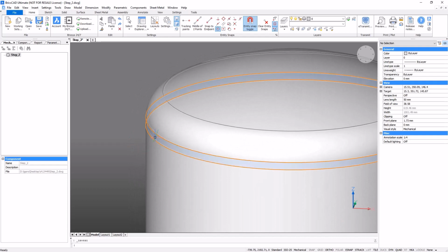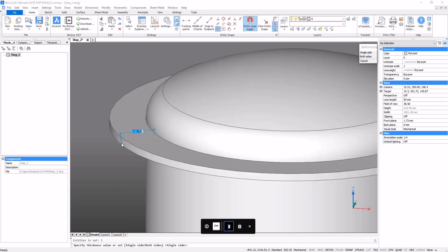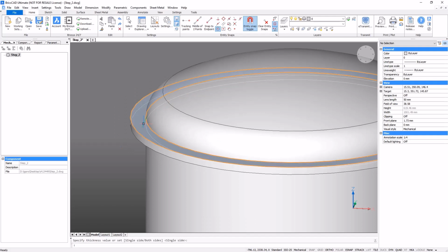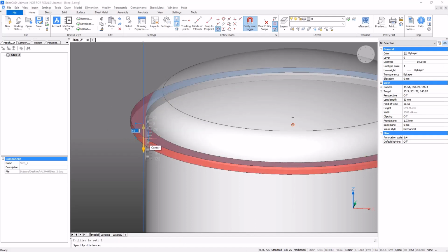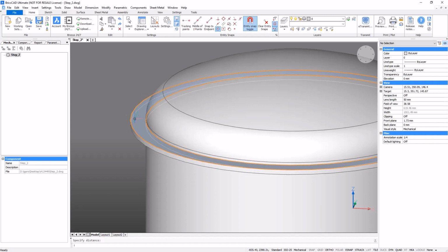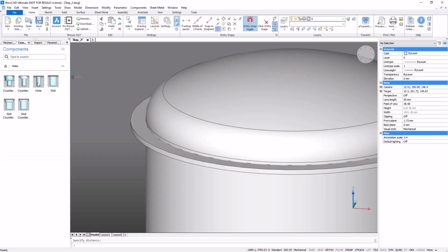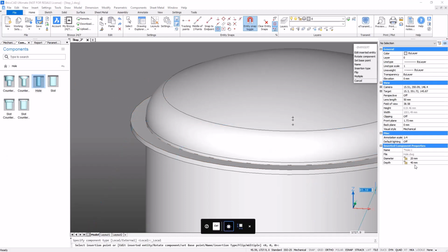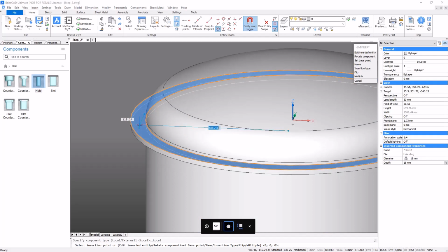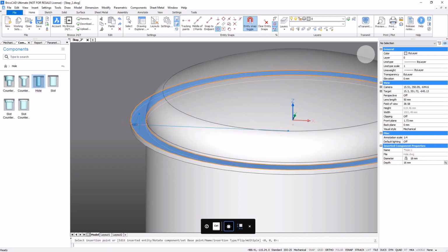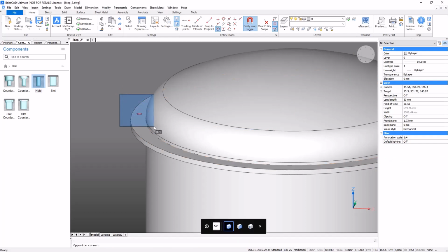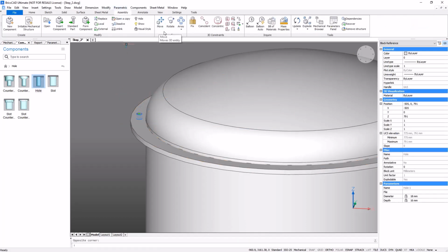The next part is where we create the flange, again by using the existing edges and the faces and not by creating any more sketches. So I'll use certain direct modeling features, like this one is push-pull, wherein I need to reduce the flange thickness. Then there's this library component that I can use to place holes for fasteners at a later stage, which I'll be inserting again using my library components. And as you can see, the hole itself is parametric, wherein I was able to change the radius and the depth of the hole that I'll be placing on the flange as well.